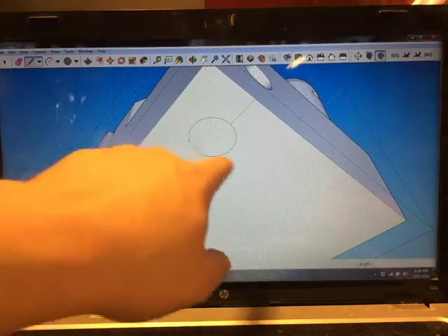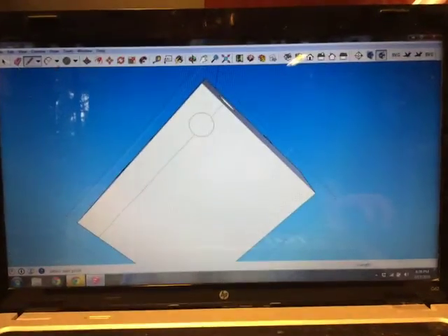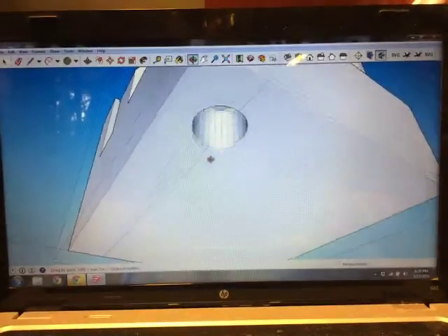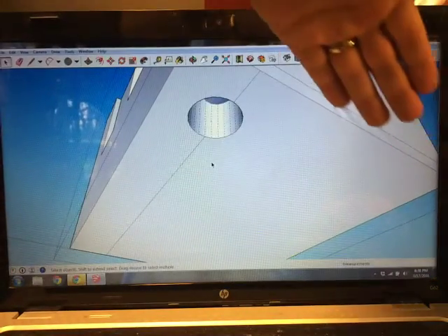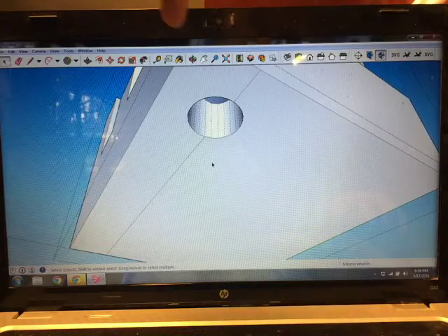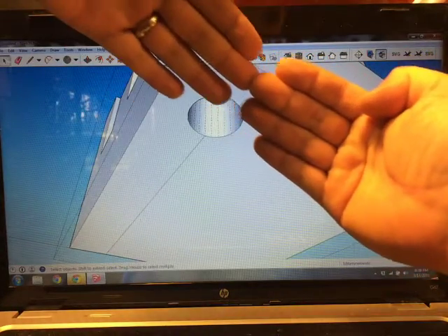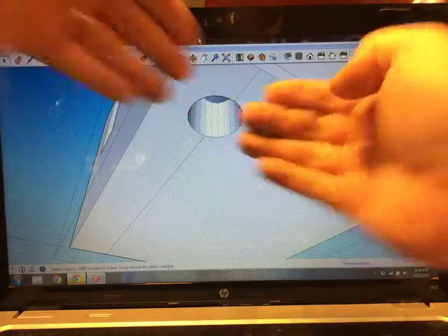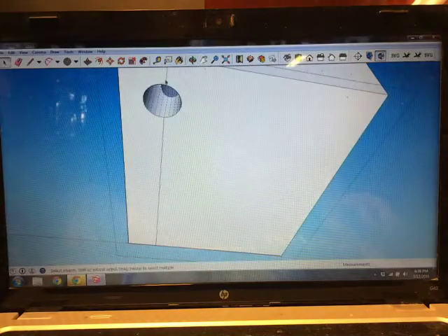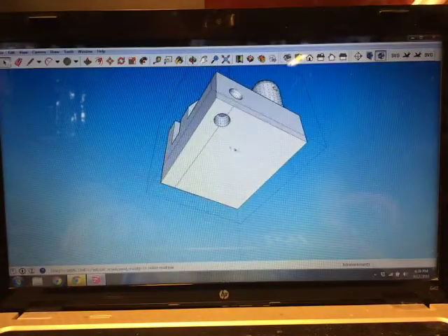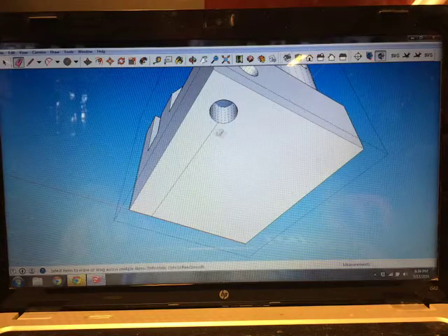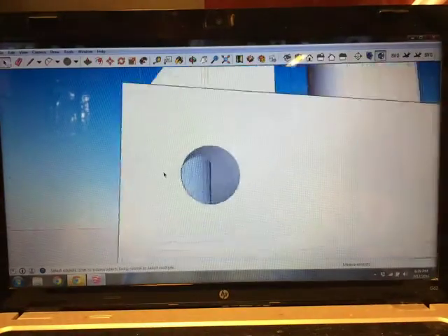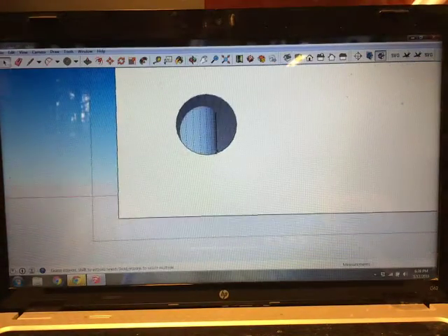Now, if you notice, this whole circle just lightened up, which means it attached to the face. So basically what we have done is we have taken this line and then slowly curved it in a new position so that it took the face and folded it together just slightly, and this curve is now slightly folded as well along this point right here. And that's a quick fix, and you can even delete these sometimes, and it will try to balance everything out mathematically. But it's a dirty way to go, and it can give you problems down the road, so at your own risk.